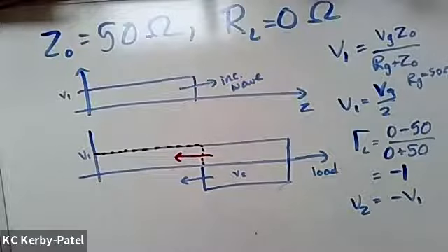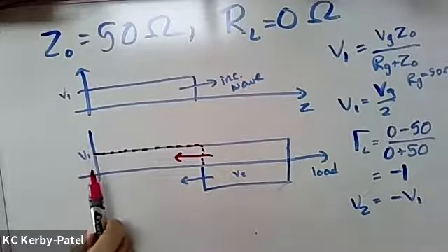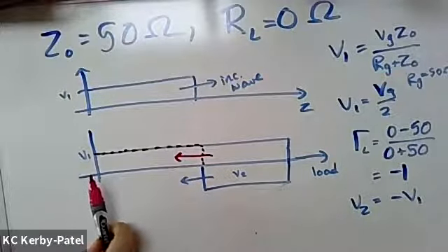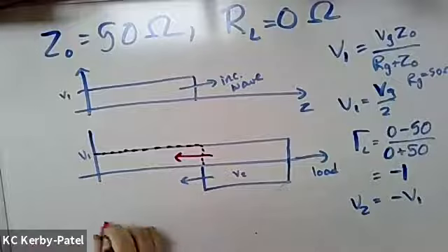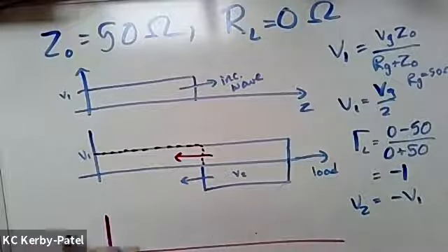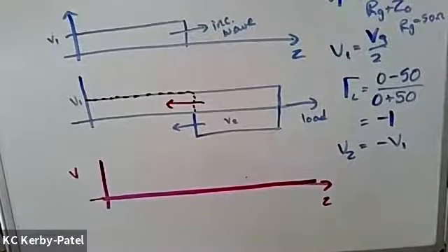Which makes sense because eventually we should have it look like a zero impedance right at the input to the transmission line, because we're at DC and wavelengths don't matter yet. At time equals end, my voltage versus position plot just looks like zero all the way across. Whoops, I didn't. There, now you can see it.